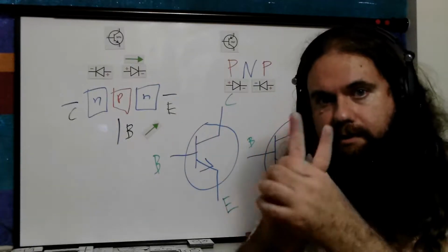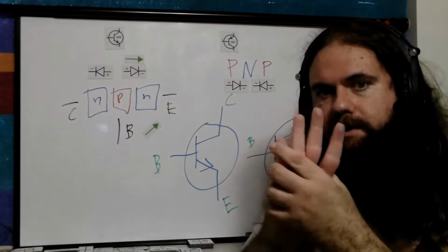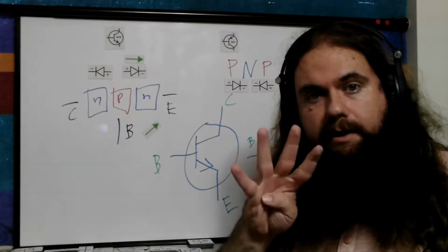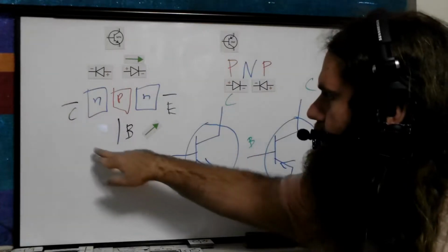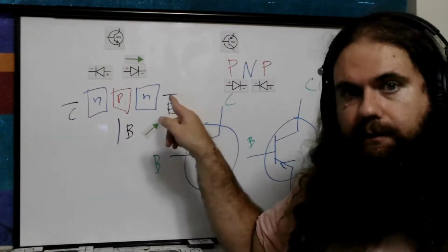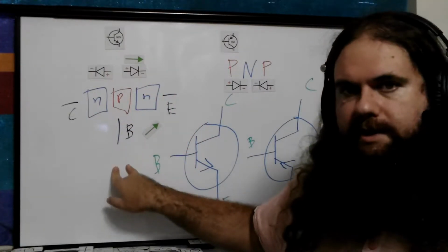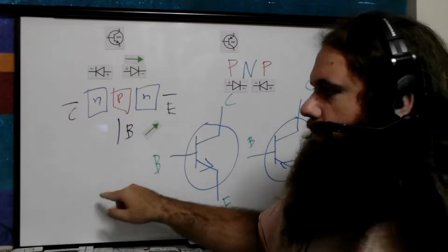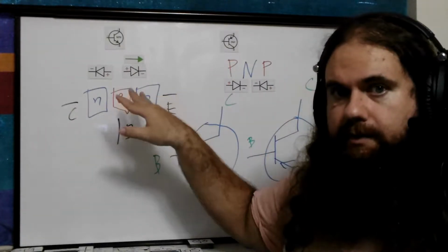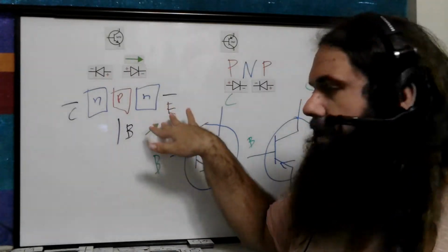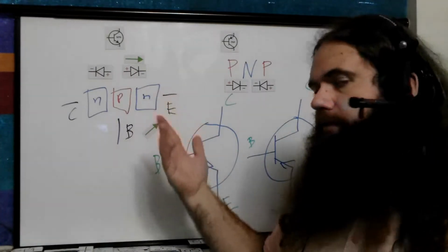You've got an input signal, which is 2 pins, an output signal, which is 2 pins, or wires. 2 wires and 2 wires for 4 wires. And then your transistor has 3 pins. How do you put 4 wires on 3 pins? Well, 2 wires are going to share one. Obviously, 2 wires of the same signal are not going to share the same pin. So 1 pin, whichever, gets 1 input wire. 1 pin gets 1 output wire. The final pin shares them.